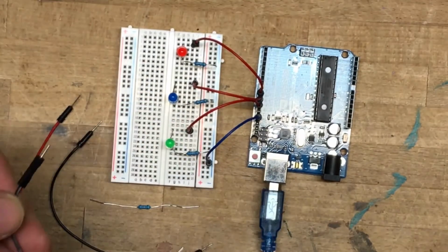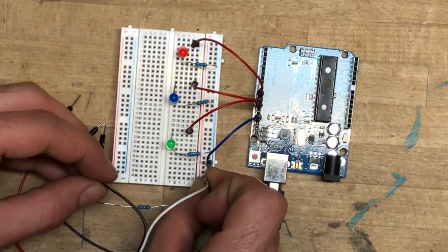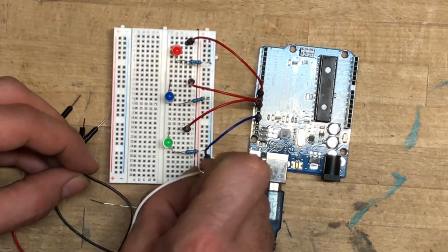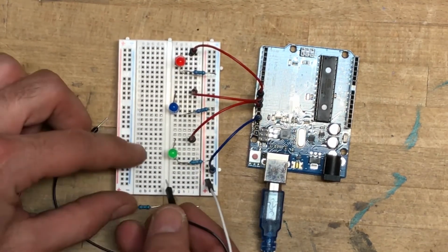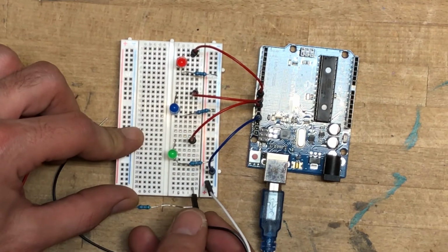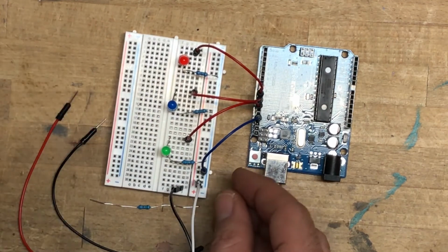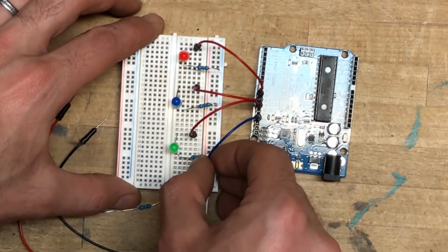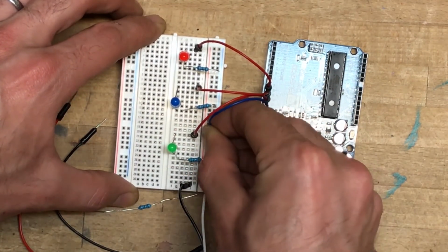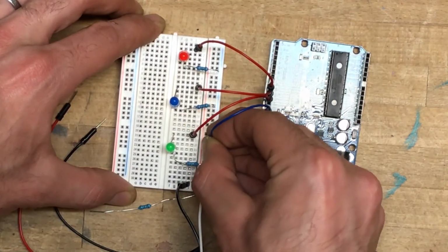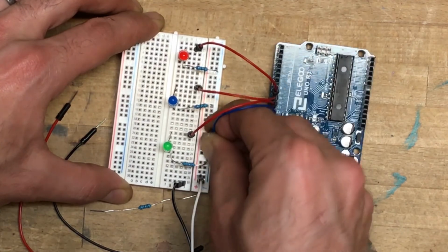Those two pins are going to go one into the positive rail. Even though we don't have power to it yet, we're going to put power to it from the Arduino. And another one, we'll just choose a random row. Let's call it the last one here, number 30. Might start to get a little crowded on this end, so I'm going to take the ground jumper and bring it back. Plug it back into the negative slot, the ground slot. Ground, negative, all the same. New boards can be a little tight. Come on. There we go.